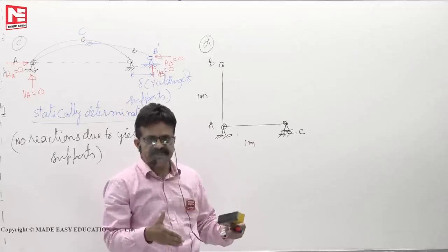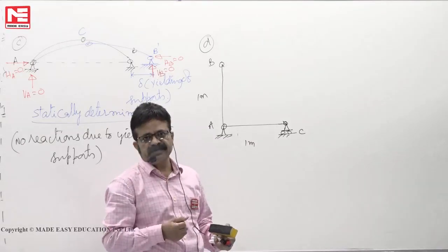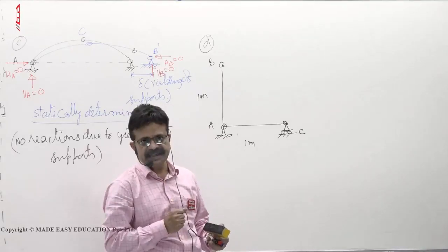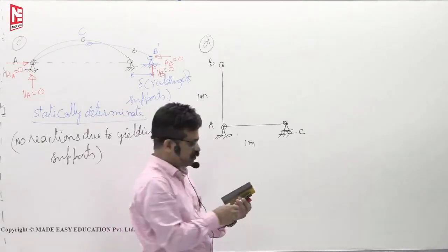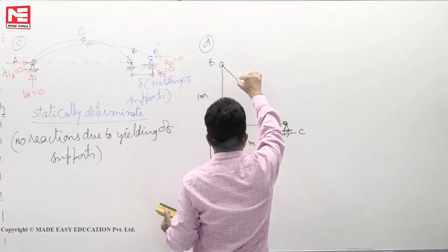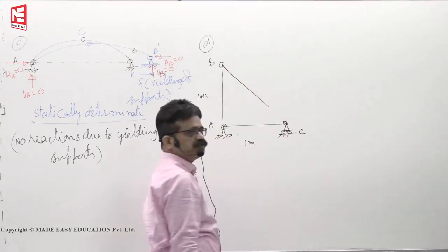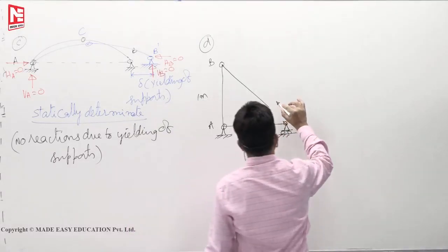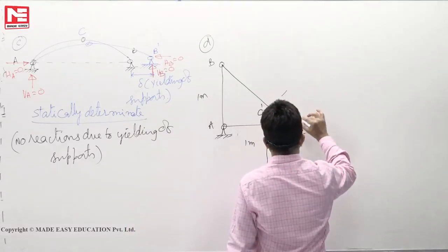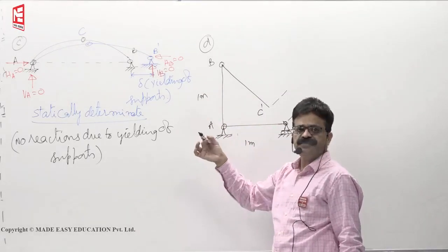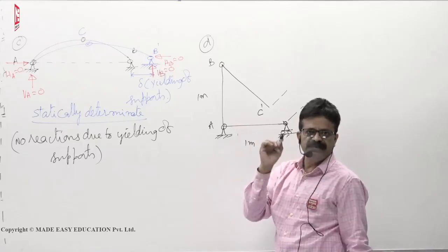What he will do in the process of cutting, he may skip off that 14 mm, he cuts only 1.4 meters, say. Then 14 mm lack of fit. That means if he cuts it such that there is a shortage, after cutting it you find that it comes only up to here. C comes to say C dash. This much he missed. Instead of cutting 1414 mm, he cuts only 1400 mm. 14 mm he forgot.